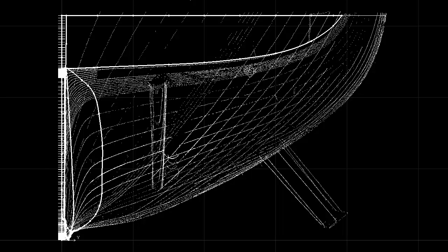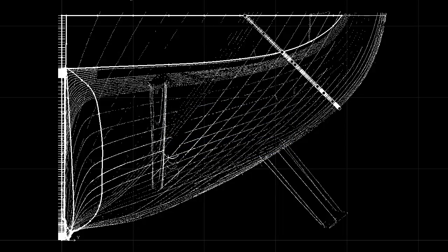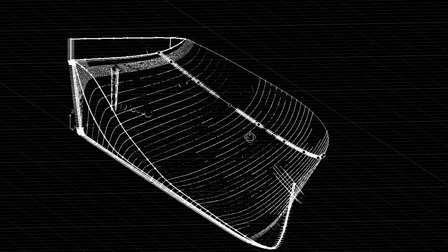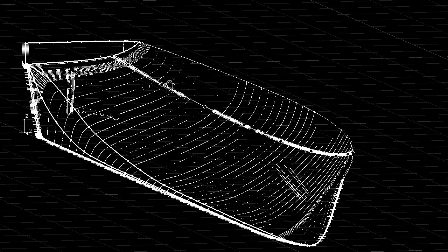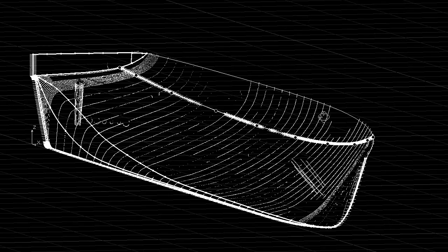So starting out, we'll use the body plan and generate a diagonal section through it, just to illustrate how this process works. So I'm effectively going to draw a plane. There we are. We have a diagonal section through the hull there. We can see all the sampled points. We see a gap and more sampled points. Now the display tells me that the mean accuracy of this curve is within 3 millimeters of the scan data, and a max deviation of 21 millimeters.